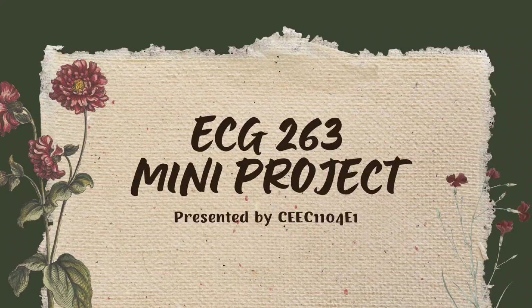test. The results show a field density of 1.09 gram per centimeter cube for A, 1.25 gram per centimeter cube for B, and 1.18 gram per centimeter cube for C. These values are slightly lower than what we achieved in the laboratory compaction test, where the maximum dry density was 1.947 gram per centimeter cube. This discrepancy indicates that the soil in the field might not be fully compacted to its optimum state, suggesting that additional compaction might be necessary to enhance the soil's load-bearing capacity.